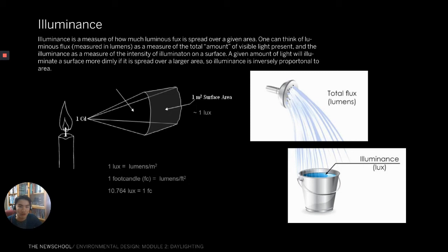While the rate at which water flows out of the fixture can be compared to the luminous flux of light, the rate at which the water is being received on a particular area of surface explains the concept of illuminance. Illuminance is therefore equal to the number of lumens falling on each square foot.